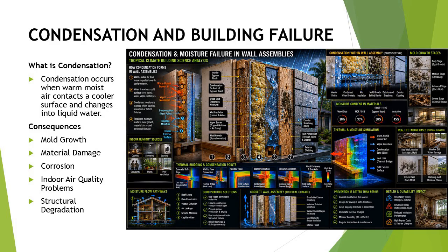In tropical climates, condensation frequently occurs inside walls, inside roofs, behind ceilings, around windows, and within air-conditioned spaces. The danger is that condensation often remains hidden. Occupants may not notice problems until significant damage has already occurred.